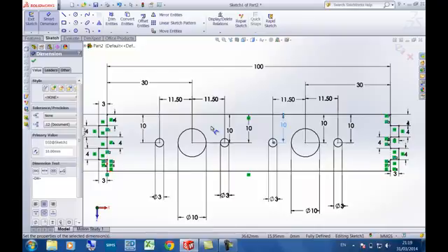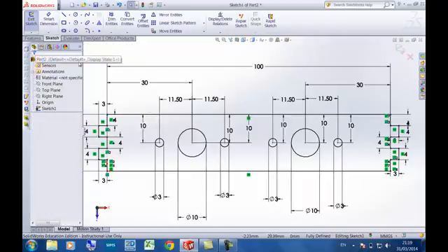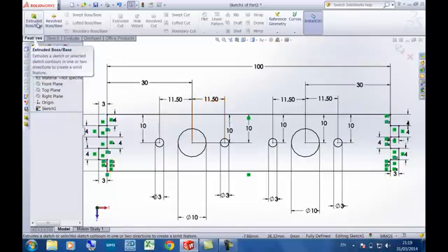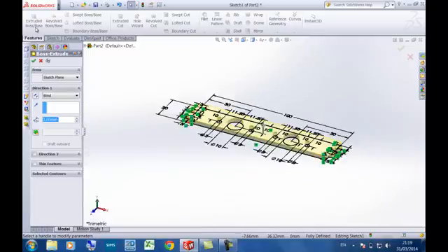Okay, now the next exciting thing is to turn this into a 3D model. So let's check this. We're done, and let's click on features. That is where we turn our lovely sketch into a 3D model. So we're going to use this feature called extrude, boss, and base. Now you can see my shape already turned into a lovely 3 dimensional shape.